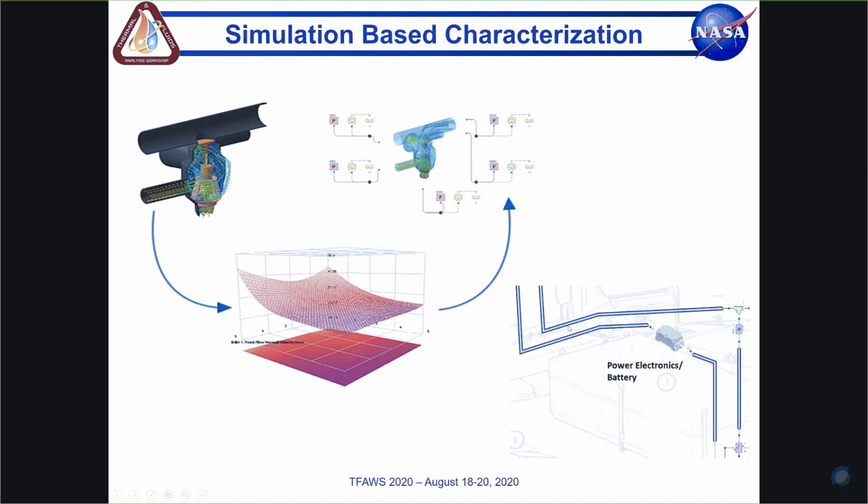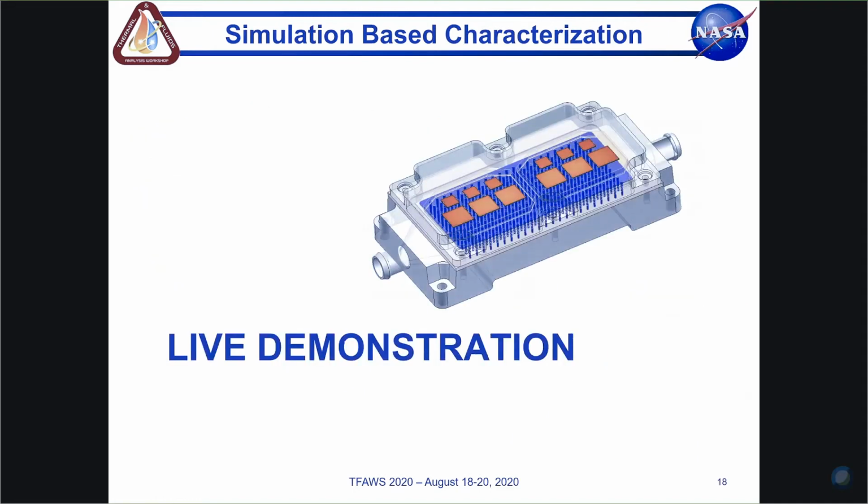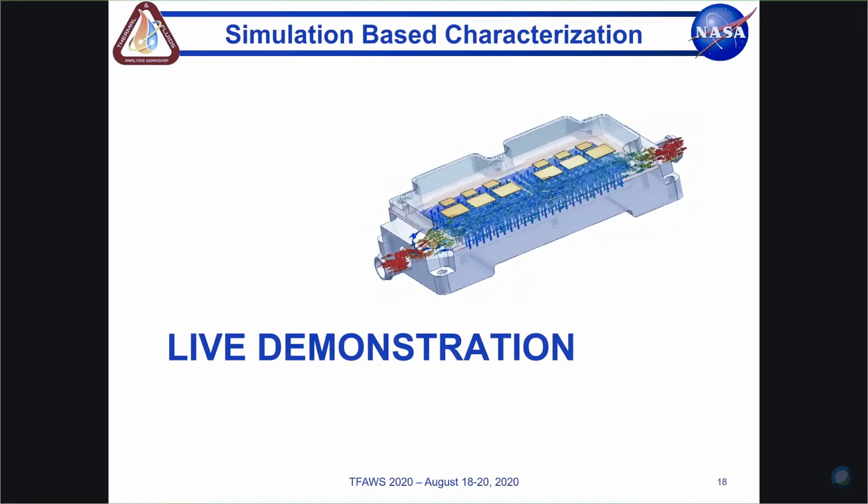So once we have that, what we want to do is build what we call a response surface model. We can do that by manually running a parametric study, exporting the data, modeling it in an external tool, reducing that data in something like Excel and bringing it back into Flowmaster. Again, I mentioned before that's time consuming and could be error prone. We can just let Flow ESD handle all the work.